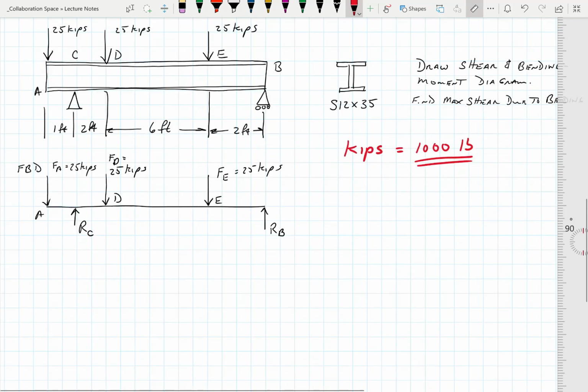Okay, we got our distances up above. We should be able to go for this. We do need to find the reactions though. So, whoops, let's put that back in black. Find the reactions. Okay, so sum of the forces in the Y can be equal to 0. But really, that's not a great place to start because we got two y's unknown, okay?